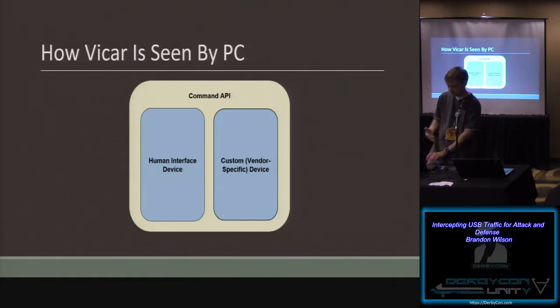Unfortunately, however, HID is not that great for sending variable length command packets, only sending a fixed data report each time because it's intended to send back structured report data like key presses. So in this mode, I made all packets 128 bytes, which can be slow and wasteful because every time you want to send a command to tell it to do something, you're sending 128 bytes over the wire.